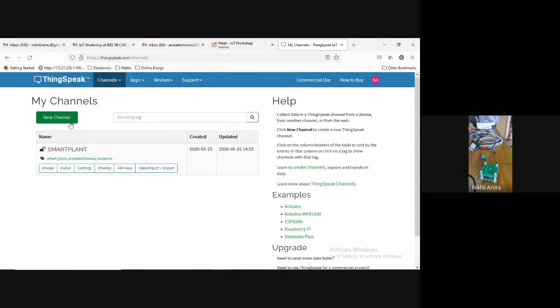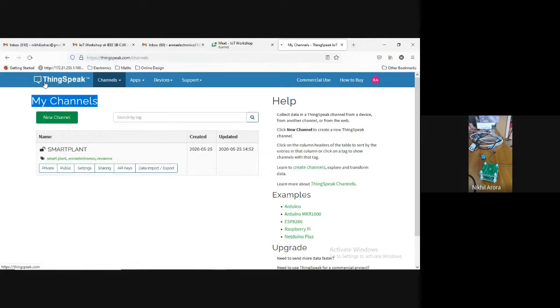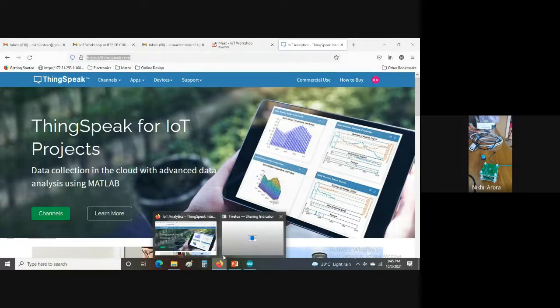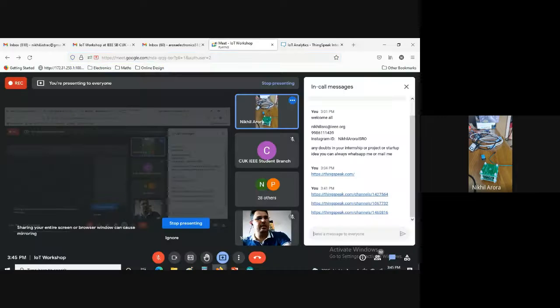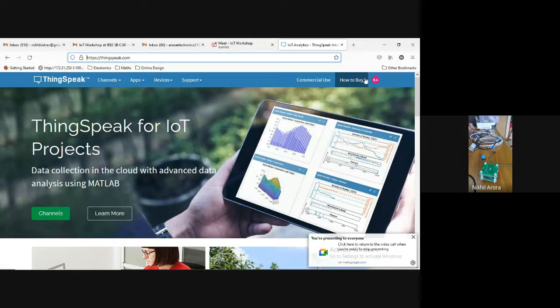So now we'll understand step by step how to create a new channel. I hope people might have signed up and generated a login ID and password for thingspeak.com. Again, I'll share the link. If somebody is pending, they can do it. Please sign up and log in. Okay. Now we'll create a new channel.